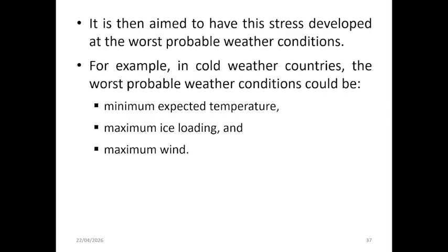In cold climate regions, these worst probable conditions typically include a combination of minimum expected temperature, maximum ice loading, and maximum wind pressure. So you have to take into account these three parameters. And each of these factors contributes differently to the overall mechanical loading of the conductor.